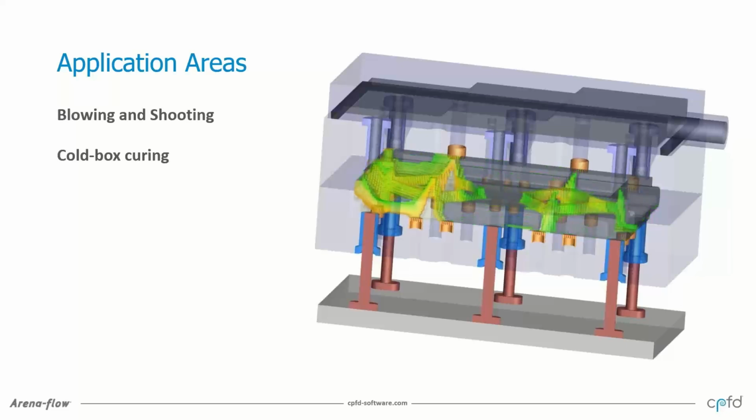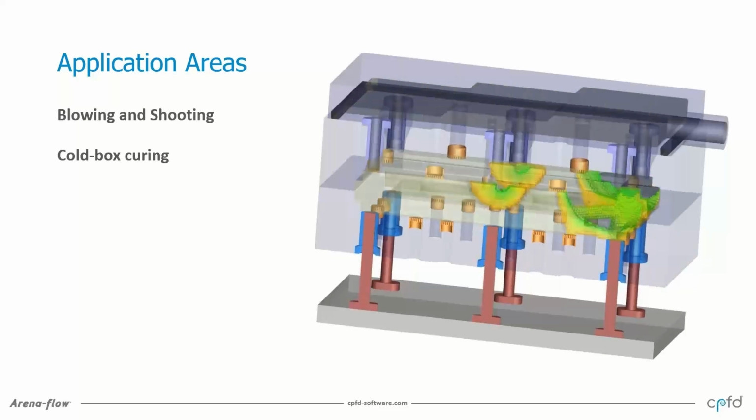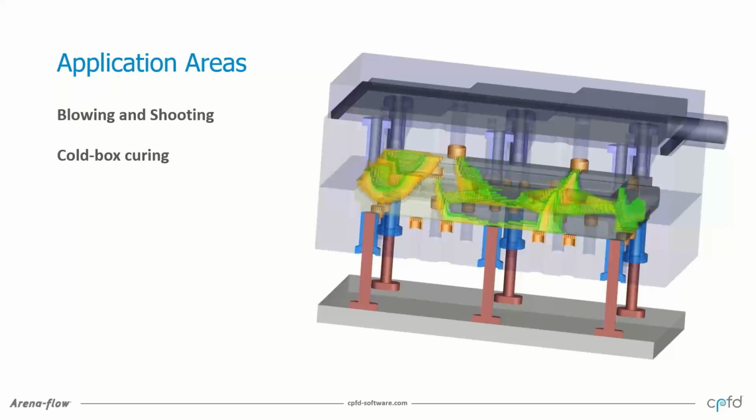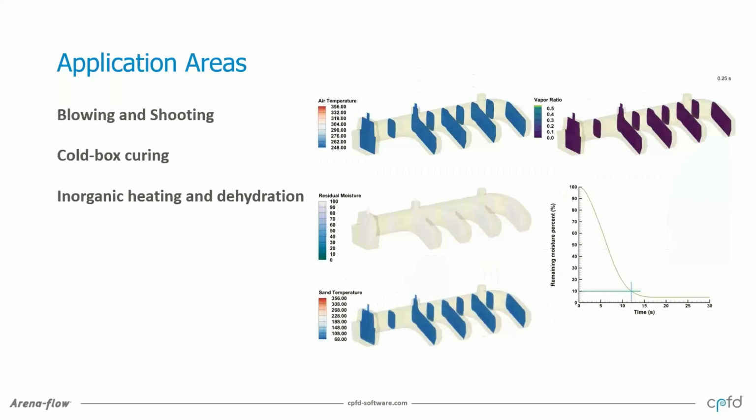So curing of cold box cores, be it amine, SO2, looking at how the curing front moves through the core. In this case, you're looking at the areas that are last to cure. These are the ones that could be uncured. Typically, they're resulting in extended cycle times. As this loops again, you're going to see areas that are first to cure, so areas that bypass the drag side very quickly. This is where you're using excess consumables. And so really looking for that optimized cure.